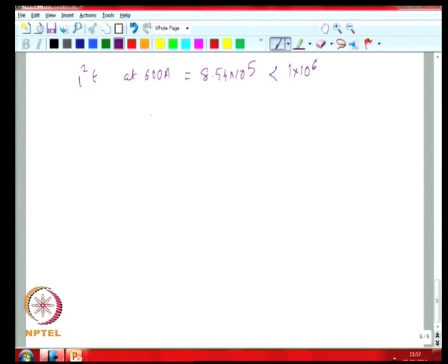If you look at the 450 amp level, you get 8.9. So, again, in case there is a failure in the protection in its local zone, then the CB2 settings will not cause the fault to propagate into zone 2. Okay. So, there is backup protection.